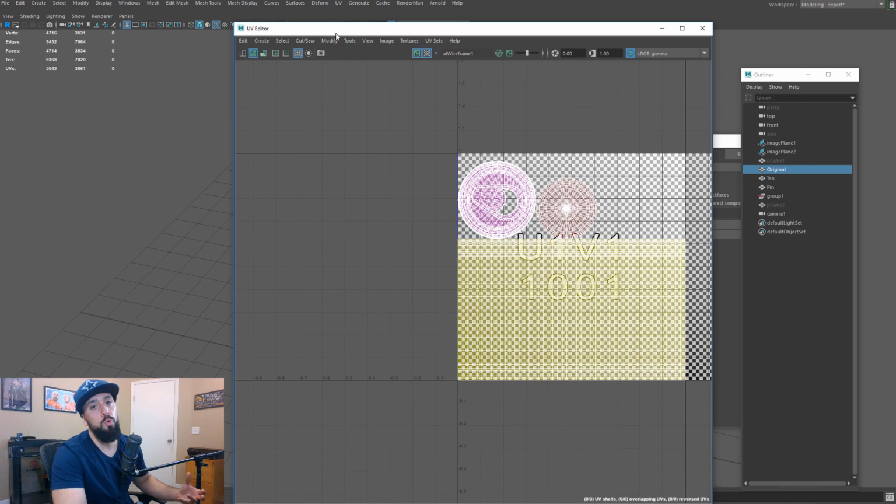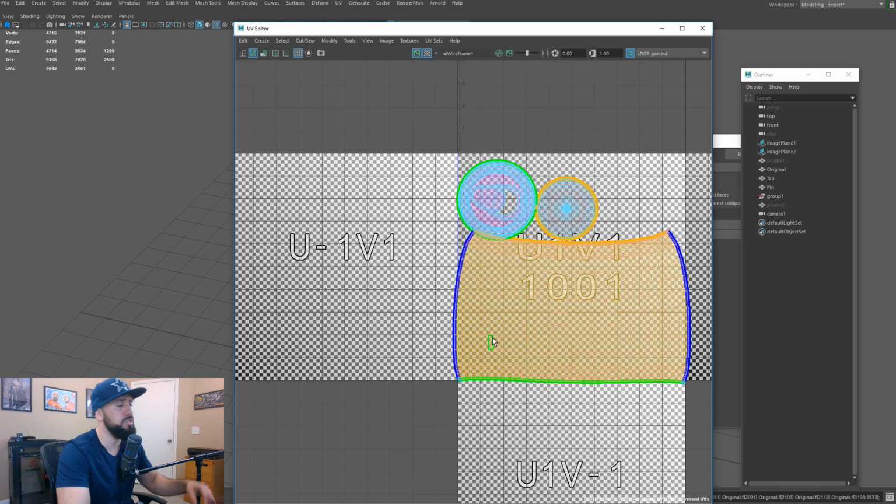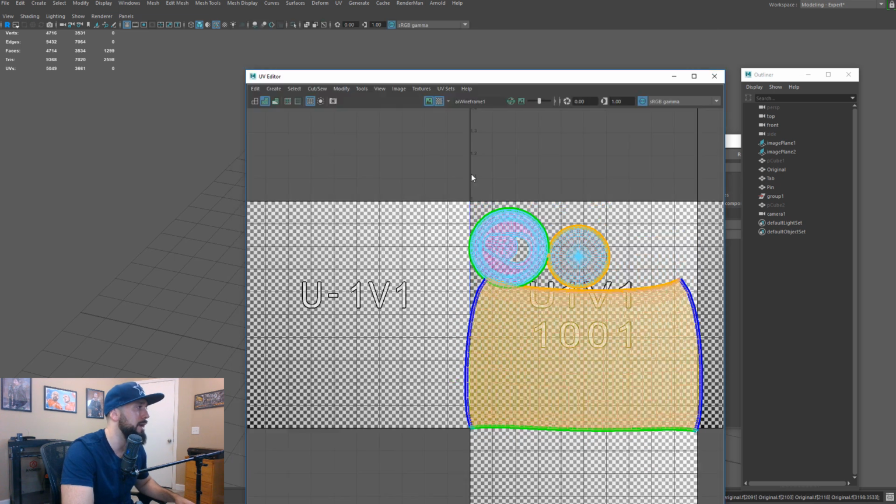So some of you might be wondering, well, why didn't you use the straighten UV tool within Maya? That tool works sometimes when it wants and sometimes when it doesn't. If you're unaware of the tool, what I recommend is you run it and see what happens. I already tried this and it didn't work on this particular object, but I'm just going to go here and, with this guy, I'll go ahead and get my unfold, which just goes back to the layout that I had.